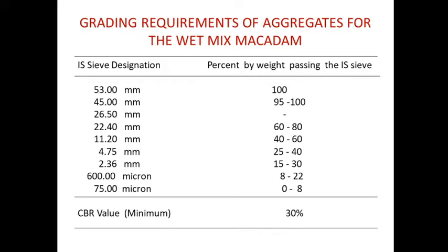Next, pavement. So the flexible pavement, that is bituminous pavement, uses bitumen as a binding material. Any idea about bitumen? Bitumen is from destructive distillation of petroleum products, whereas road tar is from destructive distillation of coal and wood.